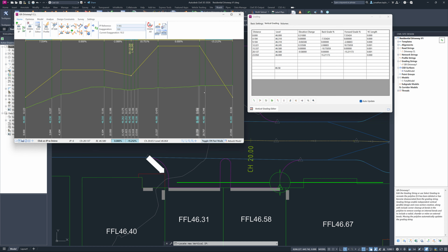So now we've set these manually, we now want to reference the road design for the start, the middle, and the end. And we're now going to look at building what we call a surface extend to help us manage that.